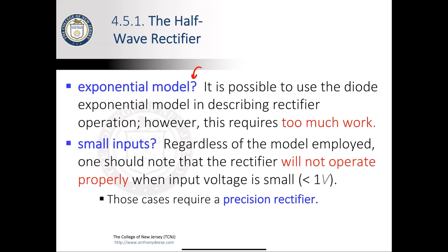Is it possible to use the exponential model to describe rectifier operation? Yes, you could, but it is going to require a lot of work, especially when you're analyzing something in the time domain, where you have to do these calculations for every point along the waveform. So I definitely would not recommend that.